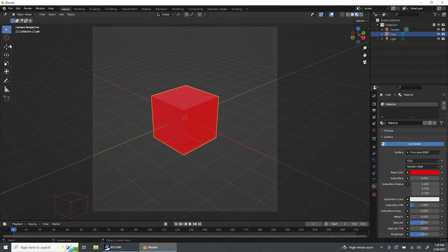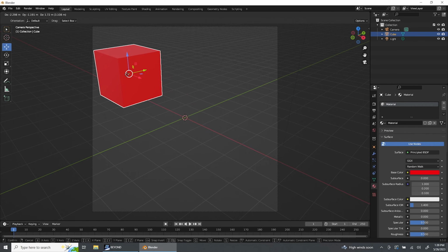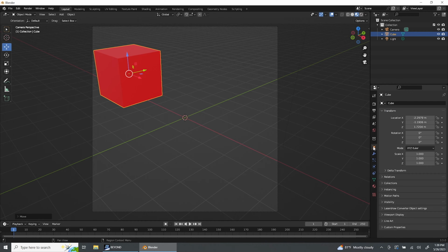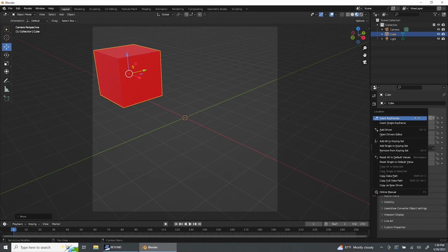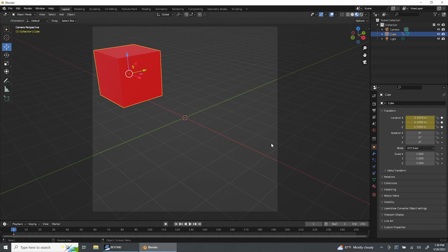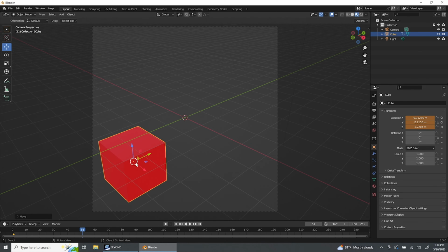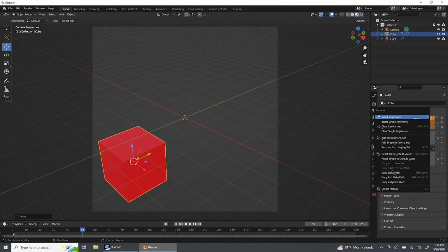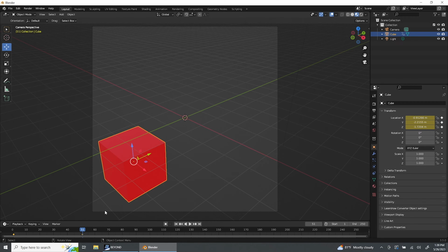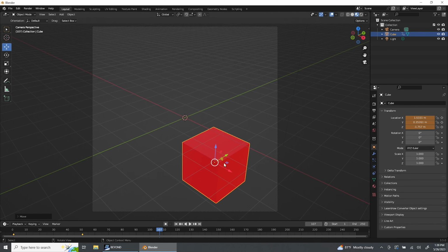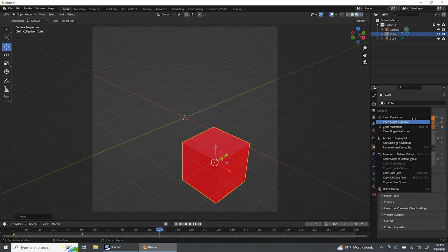So we'll create a little scene here. I'll click on the Move tool and move this cube to an initial position. Click on the object settings and just move and make a keyframe in that position. I'll move the time slider to a different time, drag the cube to a different location, and make a keyframe in this location, and repeat this several times, just as a demonstration of how to do things.